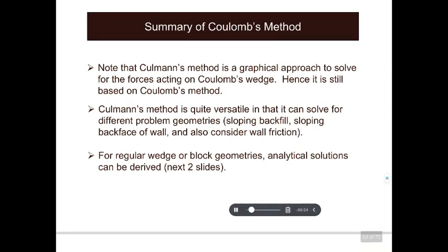Now, note that the Culmann method is a graphical approach to solve the forces acting on the Coulomb wedge, hence it is still based on the Coulomb method. The Culmann method is quite versatile in that it can solve for different problem geometries, like a sloping backfill, a sloping back face of the wall, and it also considers wall friction. For regular wedge or block geometry, an analytical solution can be derived, and I will show you in the next 2 slides.